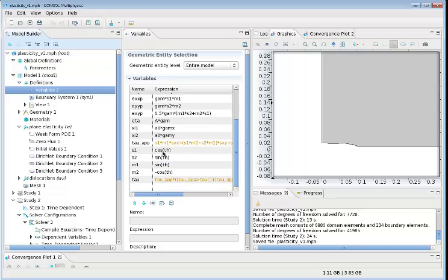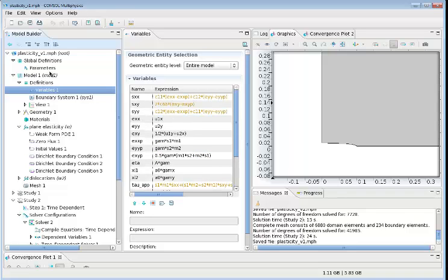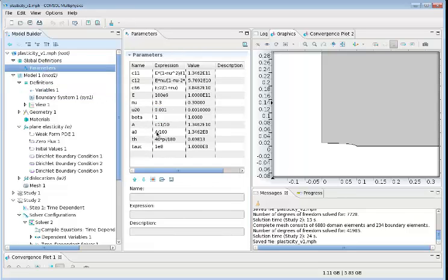I've gone through and I've checked a few angles, and I found parameters that should work reasonably well. The other thing I did is, here's the displacement I'm using on the surface. So this is what you should use for the homework. Currently I have a beta set to 1 to stabilize the problem. Here's my material coefficient resisting dislocation motion. So it's C11 divided by 10. I'm dividing this by 100. Turned out 1,000 lattice instabilities.